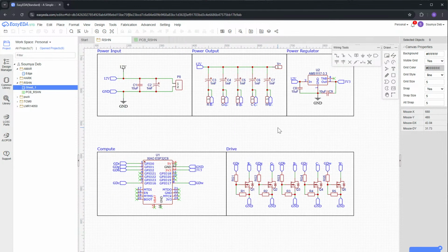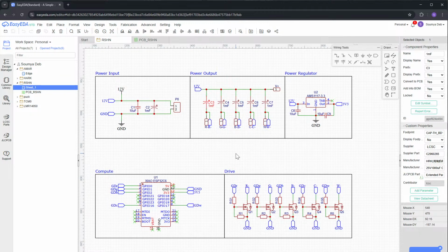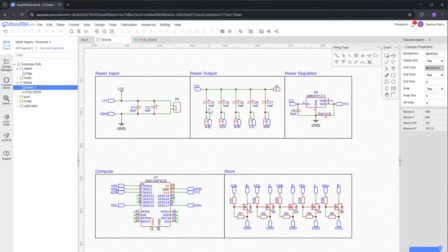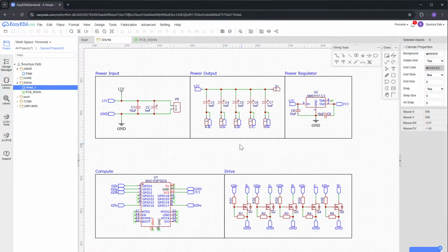So even if you're running at a very low PWM, saturation to make these capacitors charge up happens really fast. So basically, if you're 25% into dimming, probably the LEDs are all reaching the point of 12 volt and opening up fully. So that's something I was mistaken about.